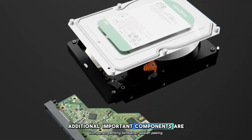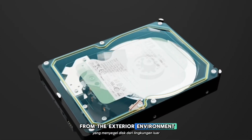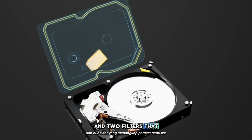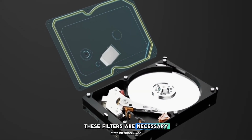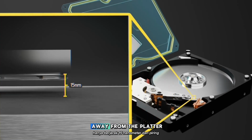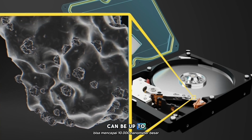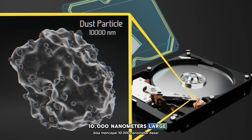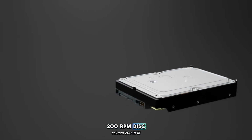Additional important components are the gasket that seals the disc from the exterior environment and two filters that catch any stray dust particles. These filters are necessary since the read-write heads are just 15 nanometers away from the platters, and a single dust particle can be up to 10,000 nanometers large, and could cause major damage if it were to collide with the 7200 RPM disc.